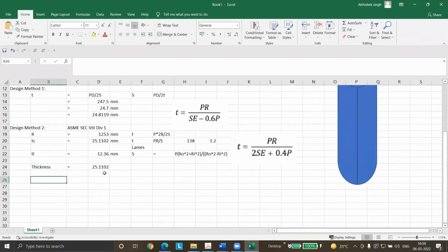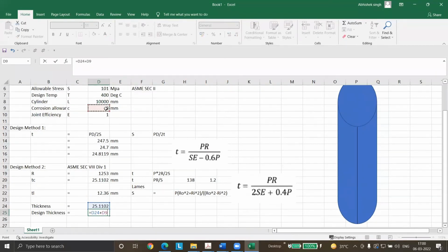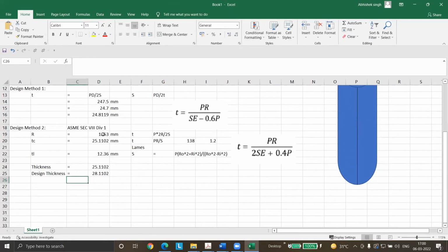Now, do I need to add corrosion allowance in this? Yes, sir. Yes, because this thickness is without any corrosion allowance, right? I removed all the corrosion allowance and then calculated the thickness. So now I need corrosion allowance, right? Everyone is getting this? Because this is the portion where many get confused. Someone may say, you added the corrosion allowance in the radius, then why again in thickness?